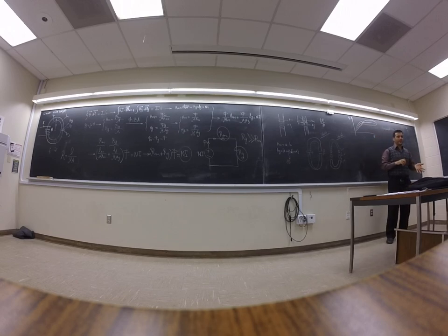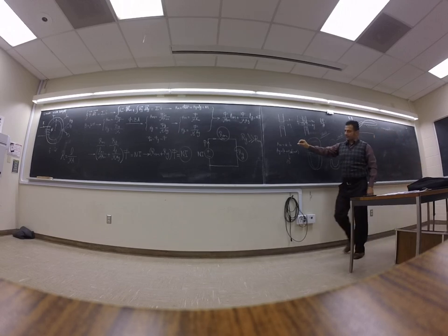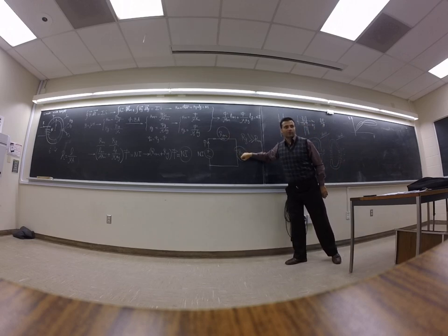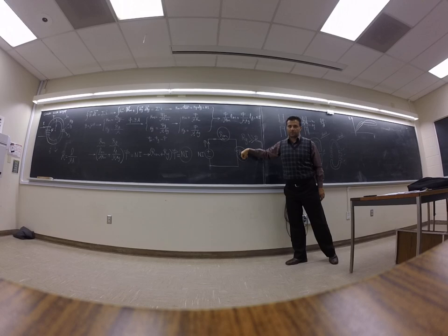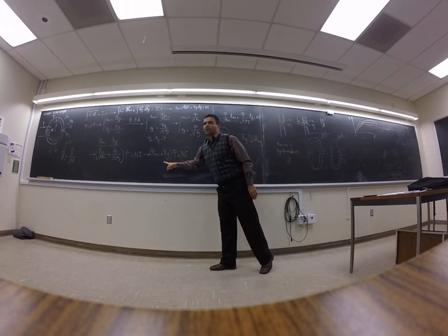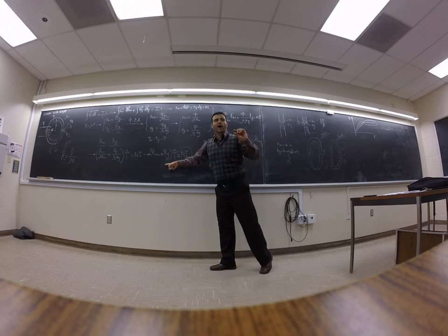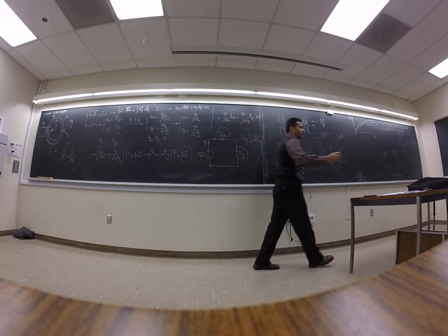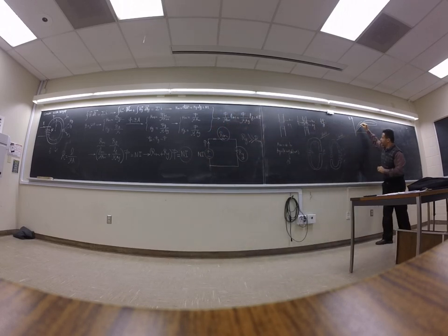To control the B, you have to have this one, which is usually small. You have to have a resistor here to control the flux, right? Look at here, flux. Flux is Ni over Rm plus Rg, right? You design your circuit. You say, I want to work with 1 Tesla, for example, 1.2 Tesla. This is 1.2 Tesla, for example, going to be here. This is part of the design. So I want to be here, right?